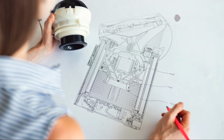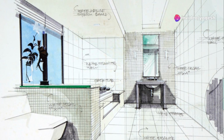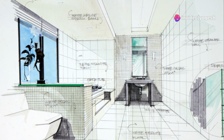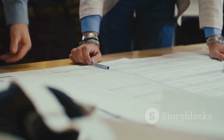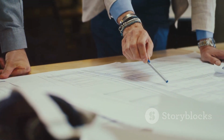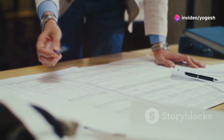Use plenty of white space to make the drawing readable. Don't be afraid of empty areas. They help separate different parts and reduce visual clutter. Guide the viewer's eye logically from view to view. Arrange your drawing so that someone can easily follow the flow of information without getting lost.